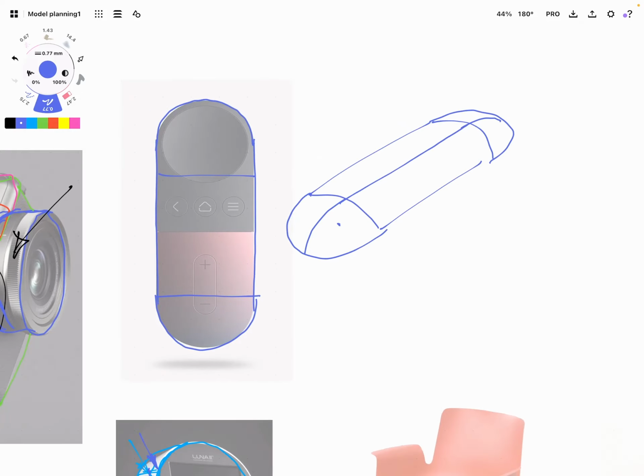To build these ends here, I've been trimming them back and trimming the surface back here like that, and then building a four-sided surface, 1, 2, 3, 4, and then use that center line as well. So that means you can have a G2 connection there and there.